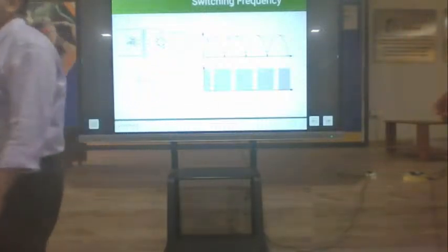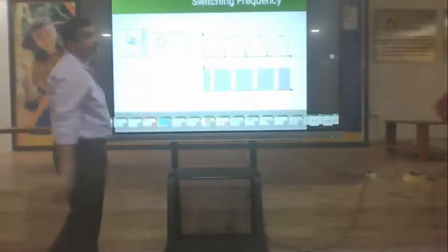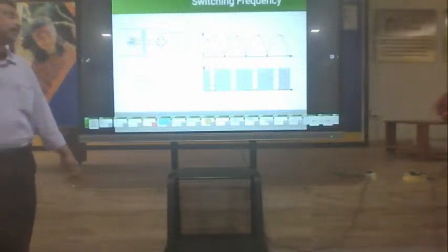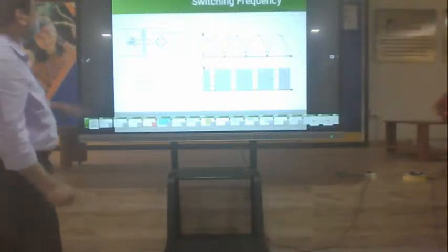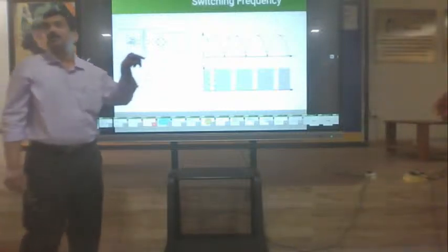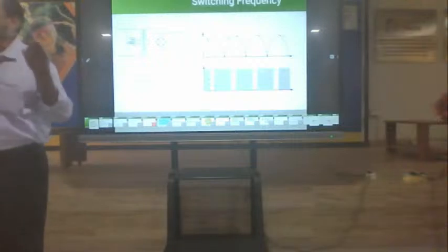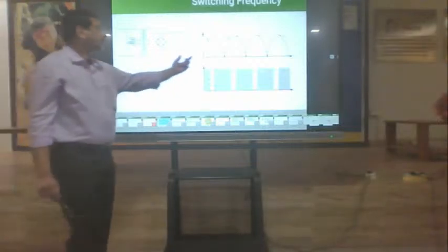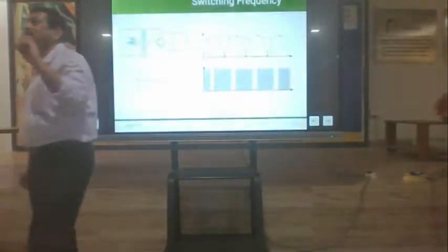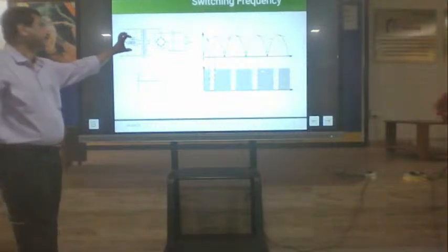So the next generation of transformers were ferrite core transformers, which support higher frequencies. With the high gain magnetics available, you can now have transformers which switch at up to 1 megahertz. As the frequency increases, the size of the energy storage required to power the load reduces, and hereby the size of the converter reduces.